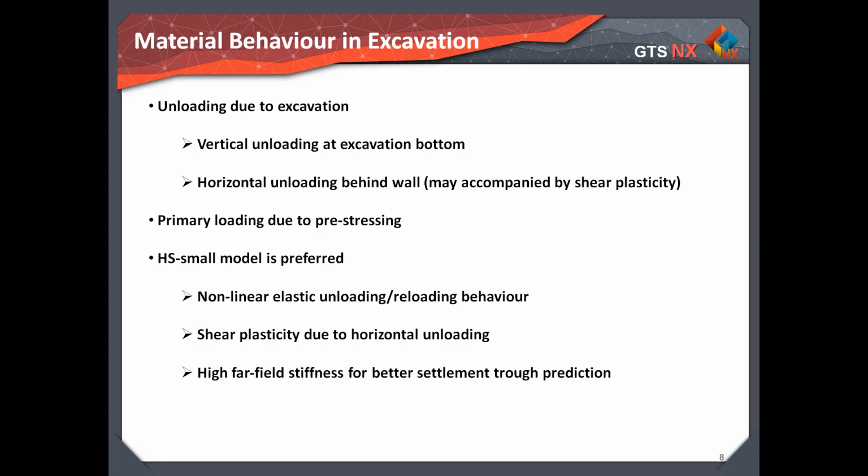The situation is different regarding vertical ground movement. Burland and Hancock illustrate this finding, for example, in their classic paper on the deep excavation at New Palace Yard in London. They assumed a linear elastic constitutive model and were able to predict the maximum measured movement relatively accurately. However, the pattern of movements predicted was inaccurate. This includes a prediction that the Big Ben clock tower would tilt in a direction exactly opposite to that which occurred.